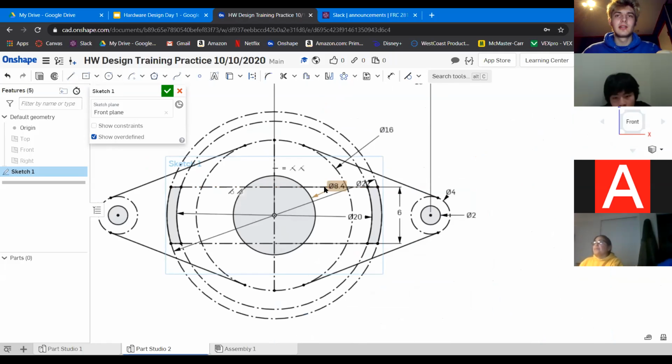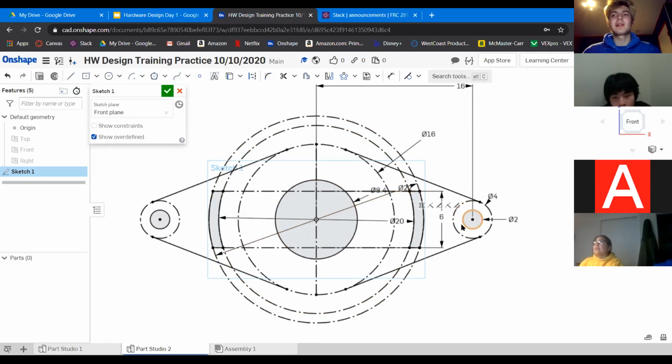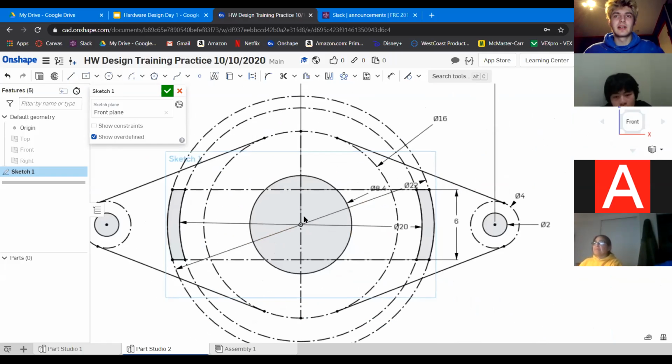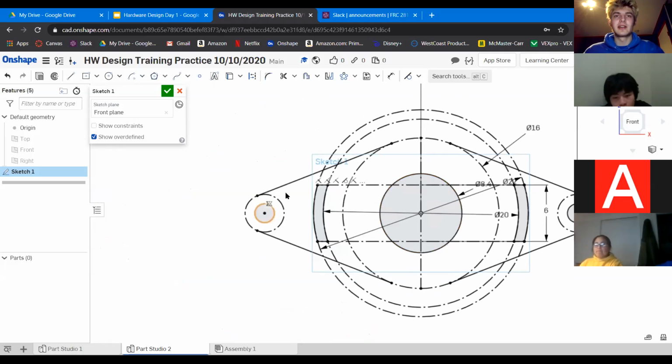And here. So we have that all done, but there's still one problem. The lines aren't grayed out, it's not a complete object. Did I go over that? Okay. So if this is a filled object, the inside of it is going to be gray. So like this circle is filled, so it's gray. This slot here is filled. It's surrounded by defined lines, so it's gray. These circles, gray. But this area here is partially surrounded by a line that is defined. But this area right here, this curve, isn't defined, so it's not contained.